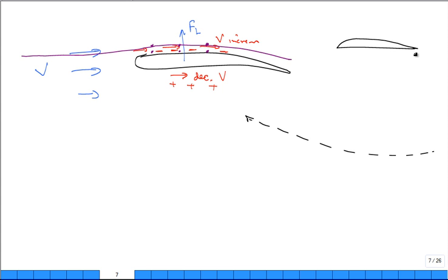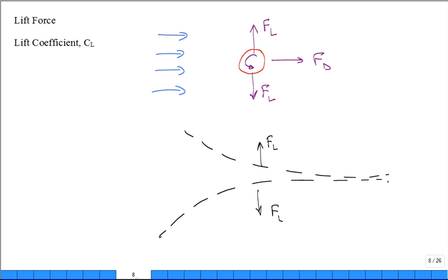Okay? Flat on the bottom and then shaped on the top like that, okay? And that would make it a negative pressure, and you would get lift, okay? So faster flow, by Bernoulli, indicates lower pressure. True? Does that help? Now I give you a minute to think about flow approaching a sphere or a ball